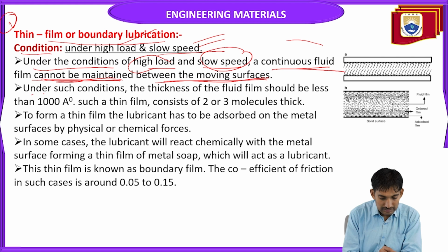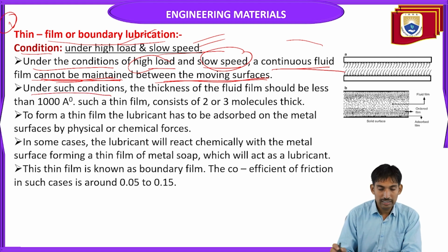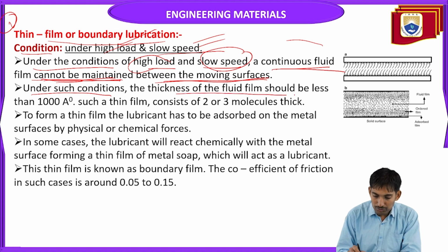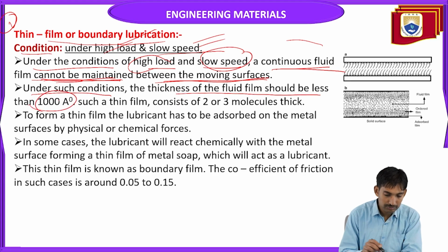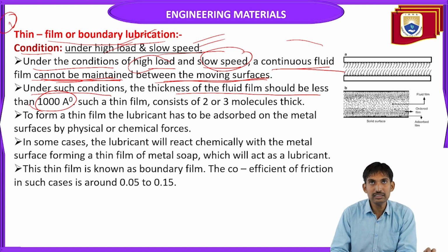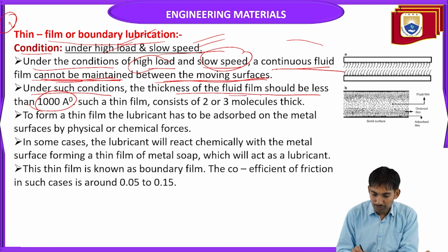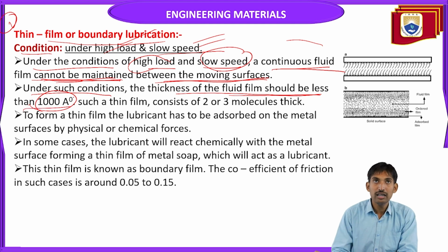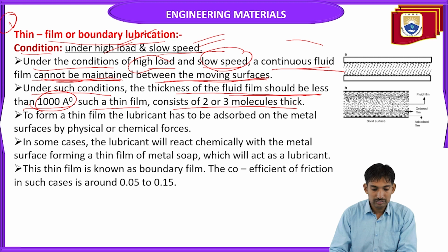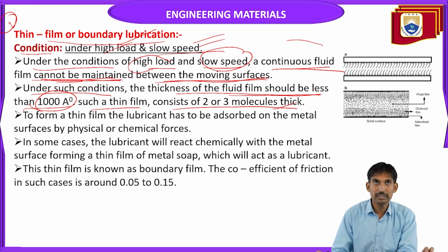Under such conditions, meaning high load and slow speed, the thickness of the fluid film should be less than 1000 angstrom. Such a thin film consists of 2 or 3 molecules thickness.